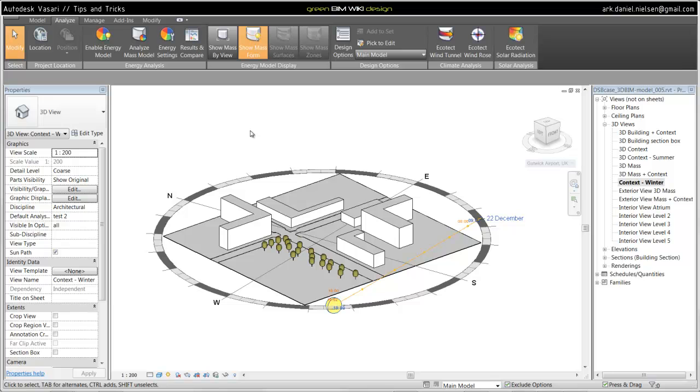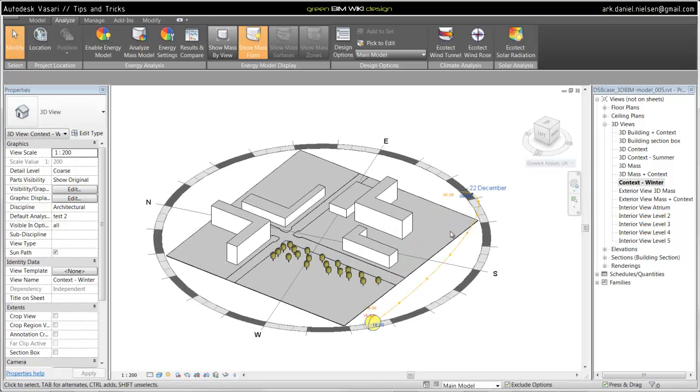The last useful tip is that you should have a bottom surface or bottom ground for your buildings, especially when you want to use the wind tunnel simulation, or else the wind can blow underneath the buildings and that will create inaccurate results. For the solar radiation, you also would like to simulate the solar radiation on the ground level.